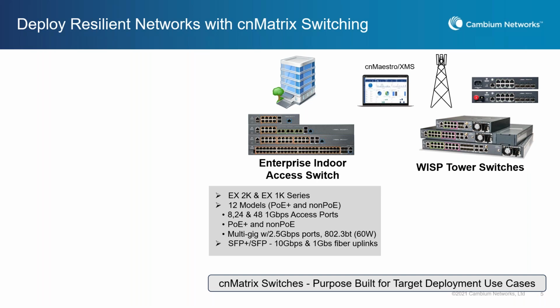Typically 99% of all the switches out there today support up to 30 watts of PoE power. That's 802.3af/at, which gives you up to 30 watts. So we do support BT on these ports, which gives you up to 60 watts. 60 watts is needed on some of the really high-end cameras, cameras that might have some mechanical movement, or some of the high-end access points as well.